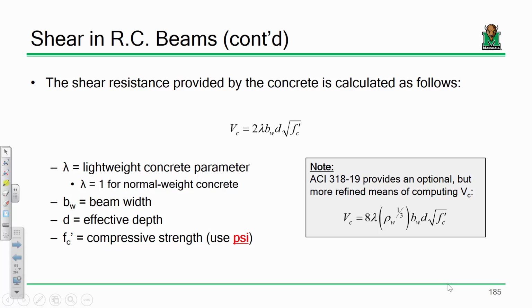When you have a beam that looks something like this, a very, very simple way of looking at it is to say that its moment capacity, its capacity to resist bending, is primarily resisted by the flanges, but its shear capacity is defined by the web, okay? So when you look at the expression for Vc, a lot of these are a function of the web, the width of the web. d is how deep it is. So you can kind of think of it as the shear capacity of the beam is sort of defined by that region there, if that makes any sense. Everybody okay with that? Now, what's going on in the gray box?